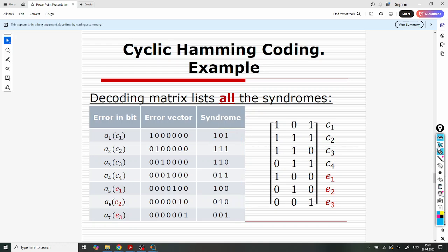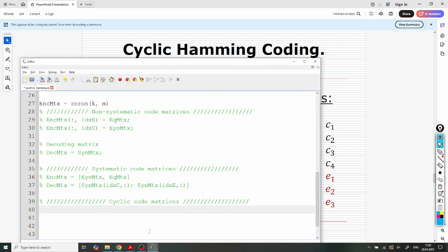So what we want to do now is to actually simulate this, going with this minimum syndrome 0, 0, 1, and going all the way up to the last one. So how should we do that? Well, the best way to organize that would be some kind of for loop where you do them one by one. So let's say that we want to have some shift register, which will be filled with 0, 0, 0, 0, 1.